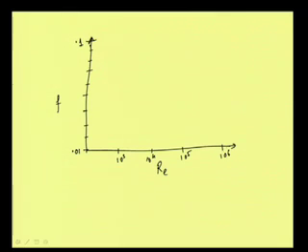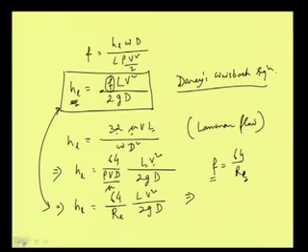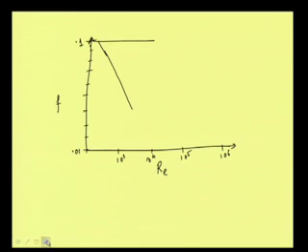What they observed is that when the Reynolds number is low, say up to 2000, the flow remains laminar. For a low Reynolds number, the friction factor varies linearly with the Reynolds number, it will come in this form. As we got in this relation, the friction factor varies linearly, of course inversely, with the Reynolds number, and that relation is indicated by our graph here. Of course, we put some dotted points here, because now it is in transition.